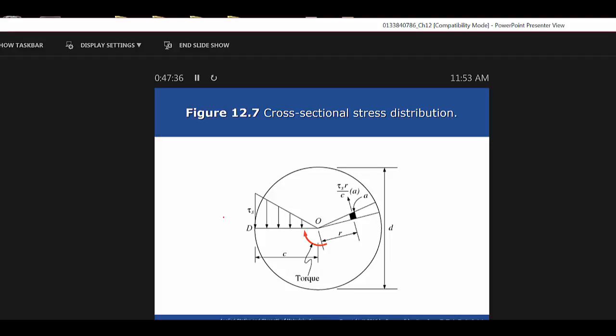So that's what they're looking at there. Actually, it would be just half of C in that picture that EF was. EF in the previous picture was right here as a point, but it would be showing up as a point in this. This is the end view of that shaft, isn't it? So that's what they're telling us. It would be half of the shear, half as much as it would be out at point D.